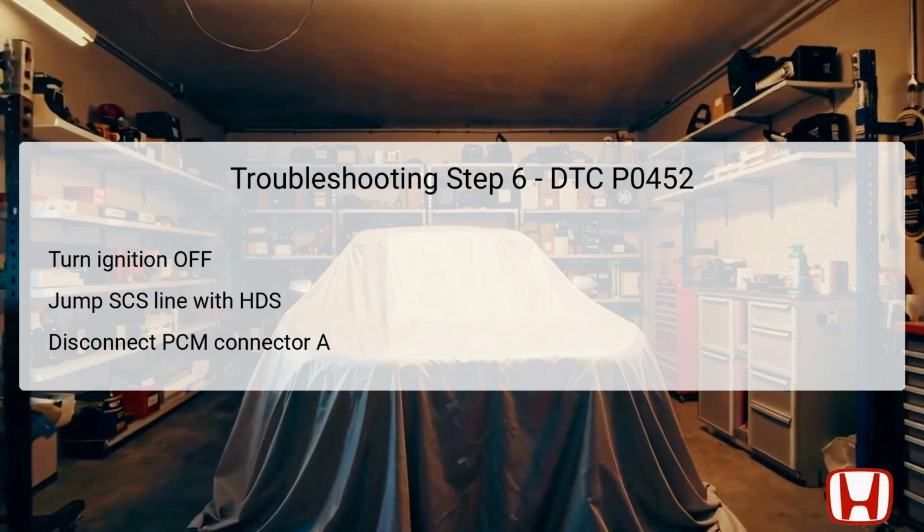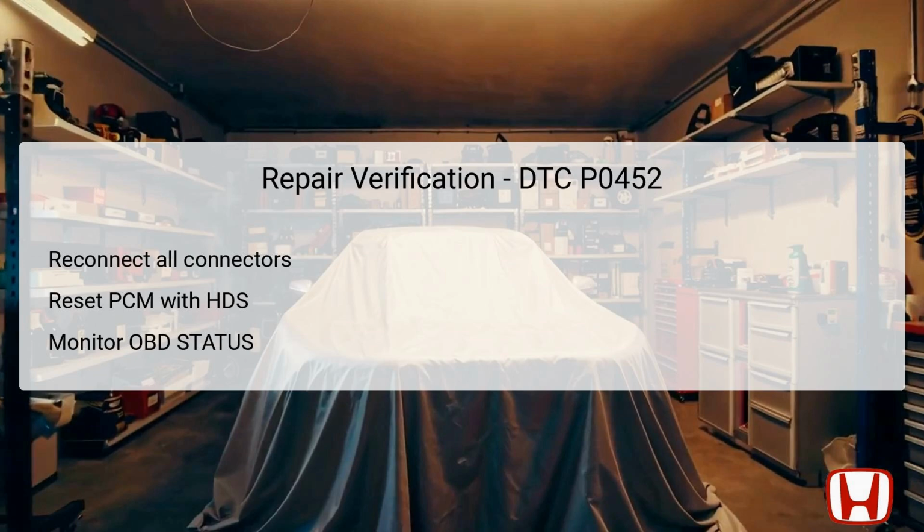If continuity exists, it suggests that the wiring is intact, and you may need to update the PCM software, or even substitute it with a known good PCM. If continuity is absent, repair an open circuit in the VCC6 wire to restore functionality. This stage is critical to ensure that the data flow between the FTP and PCM is intact before concluding any further diagnostics.